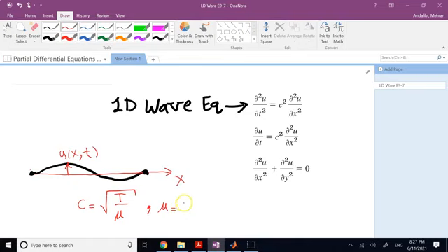So it is m over L: if the mass of the string is m and the length of it is L, then m divided by L if it's uniform. If it's not uniform, dm over dl could be mu of x in general, but here we assume that mu is constant, T is constant. So this is the wave equation, and you see this equation in vibration of continuous systems.